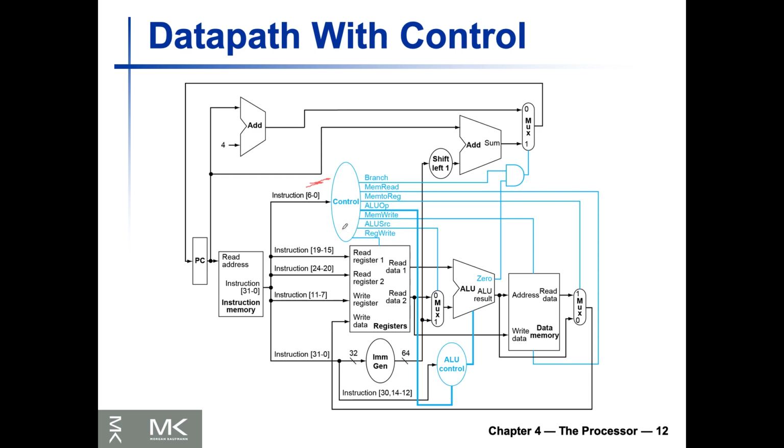Okay, that will feed to the ALU control for the ALU. One of the outputs of the ALU will be output to where we do the branch, right? That's the comparison for the branch. And one way is going to come back to the PC. And if the branch was taken, we needed another multiplexer to just go to the target branch. All right.